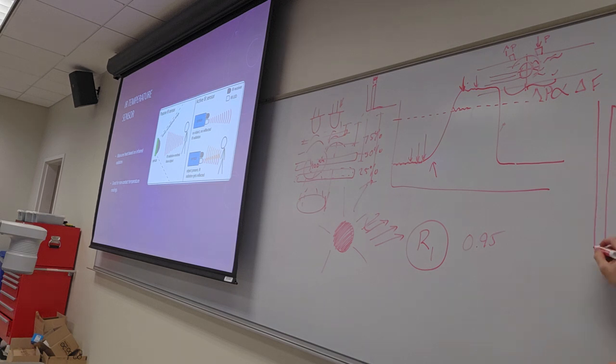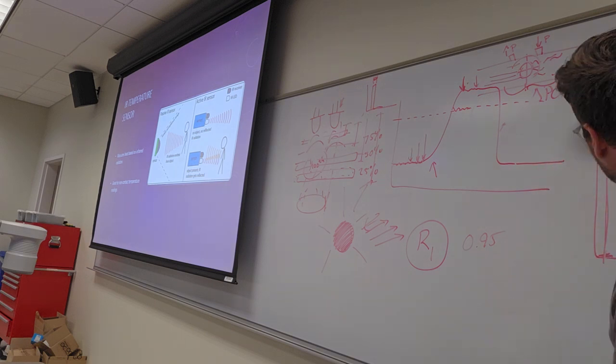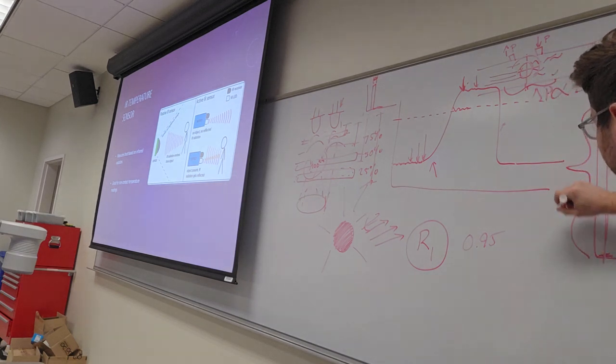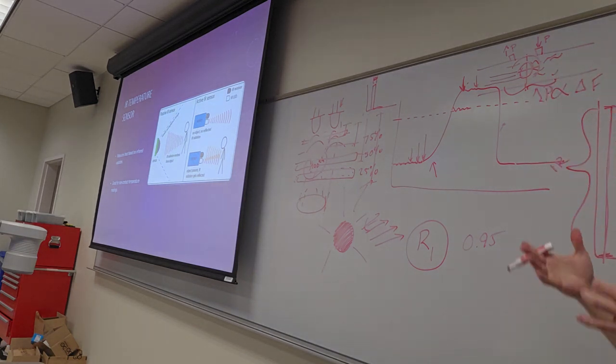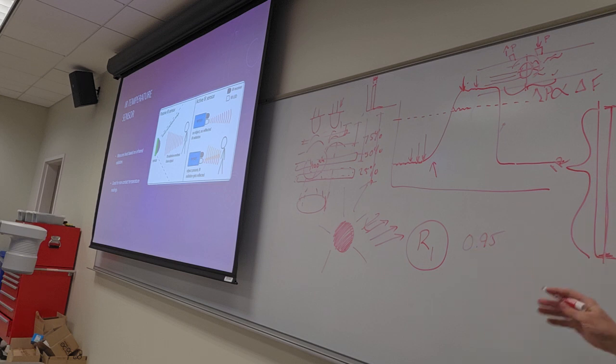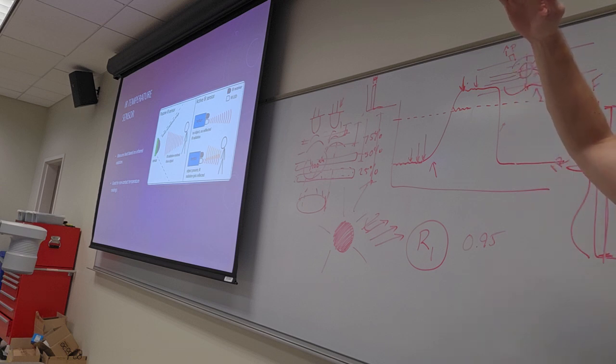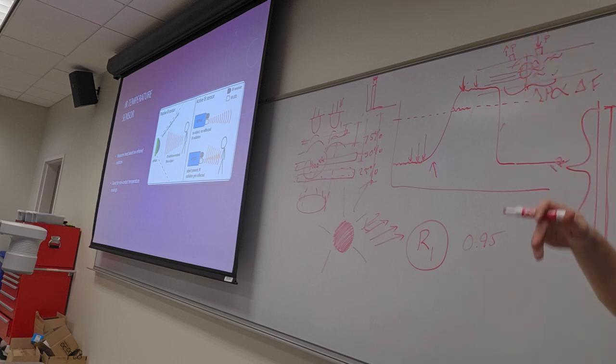Okay, so do you guys see all of this dead band information? Our actual signal is just this tiny little part. This is the only part that actually changes, like barely any at all, right? It's because all of this is the background IR junk, the light that it's seeing all the time, things giving off radiation or whatever. We're not controlling for ambient conditions. This is also what a pressure sensor would look like if you didn't kill off the ambient part, right? We would have a huge pressure signal compared to absolute vacuum or whatever, and then the actual signal would only change a little bit on top of that.